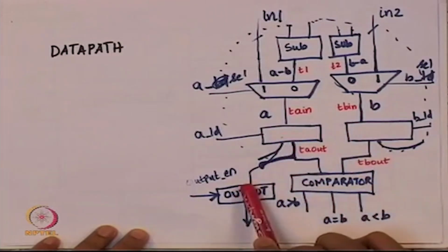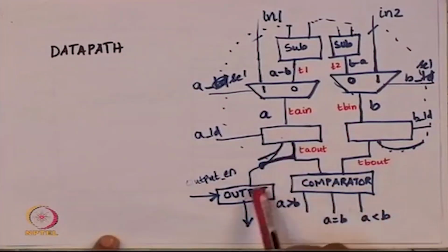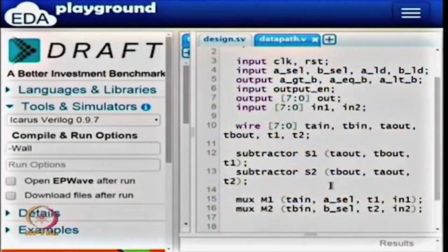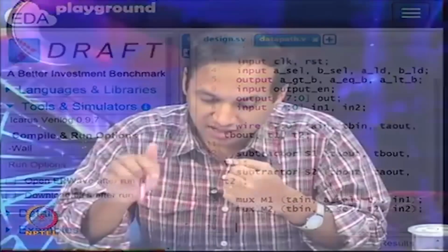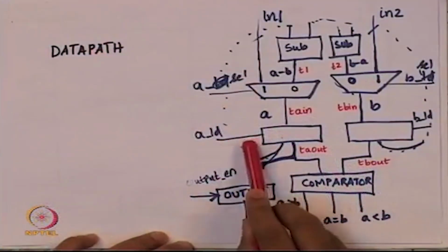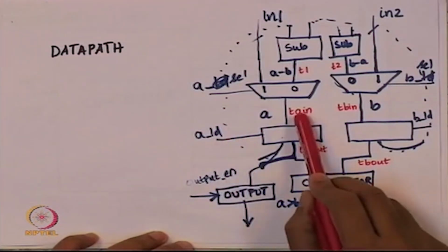There are 3 registers, and I know these are a bunch of flip flops, so they of course will take clock and reset as inputs. Besides these 2 inputs, there is an input that is coming in, there is an output, and there is a load enable. If this load enable is on, TA out is supposed to copy TA in.